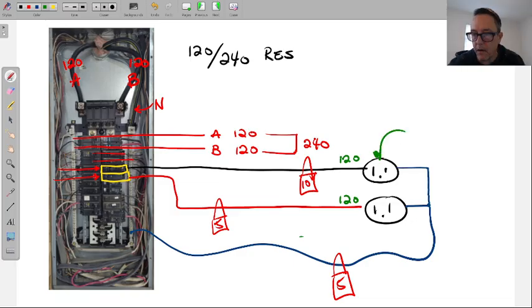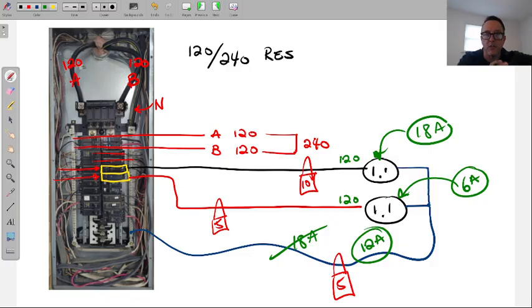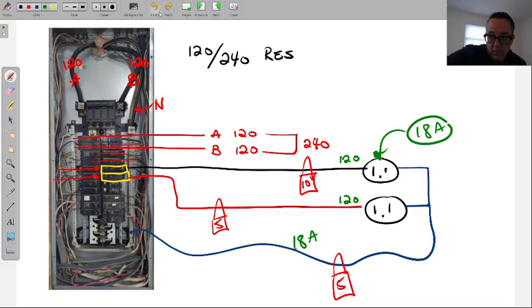If I plug into this outlet something that has 18 amps, now there's 18 on the neutral. At the same moment, you plug something in that is whatever, 6 amps. Whatever you've plugged in, minus the unbalance of 18 minus 6, 12 amps. So this is why we make sure that the neutral is the same size as the hot conductors, because potentially something else comes in and balances it. Sometimes it's at 0, sometimes it's at full capacity, sometimes it's at medium, whatever the circuit allows.